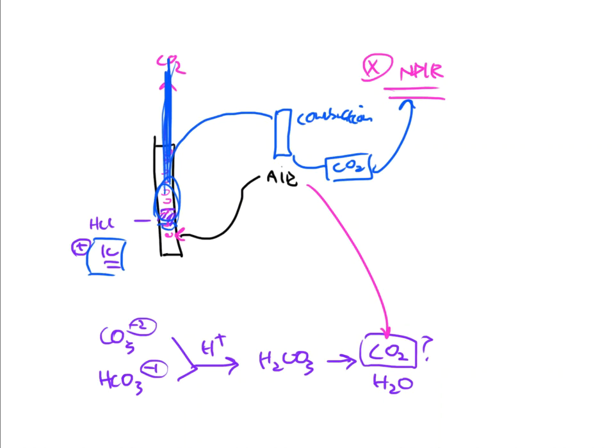Okay, so you're back. I've not run you off, hopefully, and you're here to hopefully finish this stuff up as far as pieces and parts go, right? So in the last video, we talked about the dilution water and when to replace it, every day. And we also talked about the hydrochloric acid, that 1 molar concentration for our instrument, and how to make that solution, when to replace it and make it fresh, when to load it up on the machine, and then how to replace the flow line contents to get rid of all those air bubbles and to keep that tubing line flushed and clean at all times.